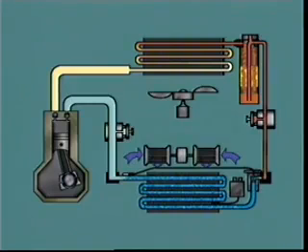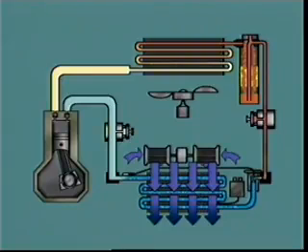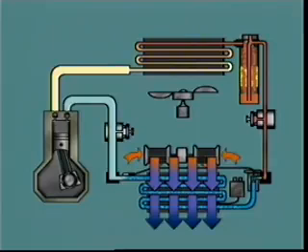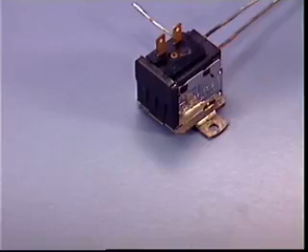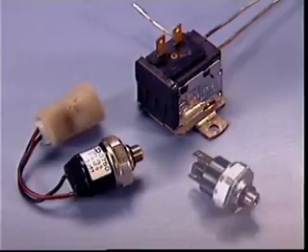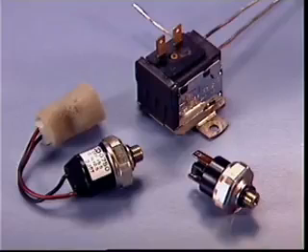The amount of refrigerant flowing depends on the quantity of heat to be removed from the air passing over the evaporator fins. More heat means that more refrigerant is required to remove it. Less heat means that less refrigerant is required. A number of control devices are fitted into the system to ensure maximum efficiency, and these operate as described in the section on the fixed orifice system.